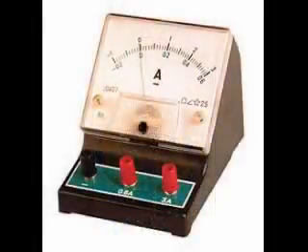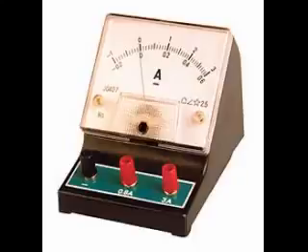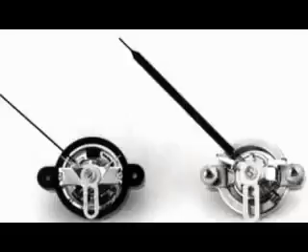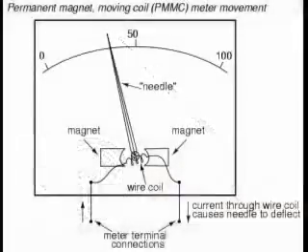Nowadays, the term galvanometer usually refers to any design of electromagnetic meter movement built for exceptional sensitivity. Practical electromagnetic meter movements can be made now where a pivoting wire coil is suspended in a strong magnetic field, shielded from the majority of outside influences. Such an instrument design is generally known as a permanent magnet moving coil, or PMMC movement.